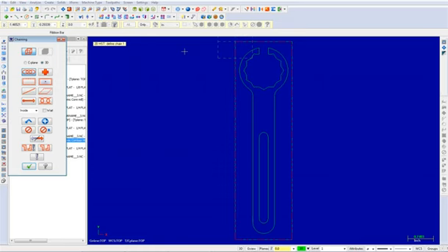When the chaining dialog box appears, enable the partial button as shown. Select the following entity. Ensure that the arrows are pointing downwards, otherwise choose the reverse button shown here. Next, choose the following entity. Once complete, select the OK button to exit the chaining dialog box.